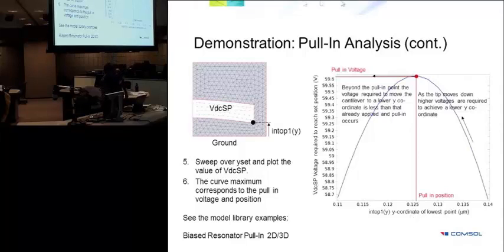That particular point corresponds to the pull-in voltage, meaning that if you were to physically, in your device, apply this particular potential, anything beyond this potential would cause the resonator to collapse. So you are at an unstable state. You cannot really solve for a stationary problem. Stationary problem meaning steady state equilibrium. You cannot have equilibrium beyond this particular potential.